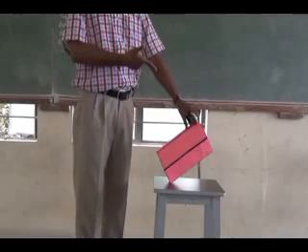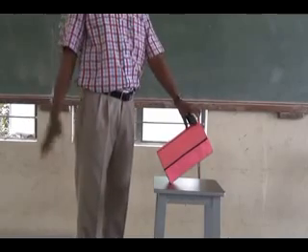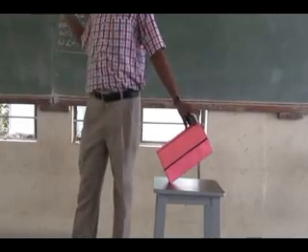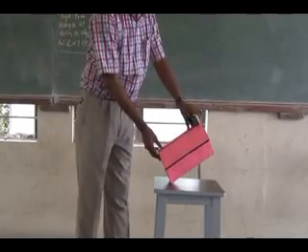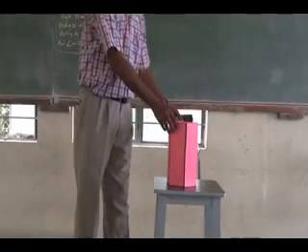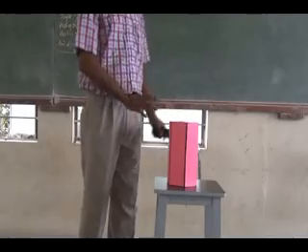As it is, straight away, I cannot draw the front view and top view. So I have to proceed with two steps. The first step: the axis is inclined to HP, so I am making it perpendicular to HP. This is a simple position.